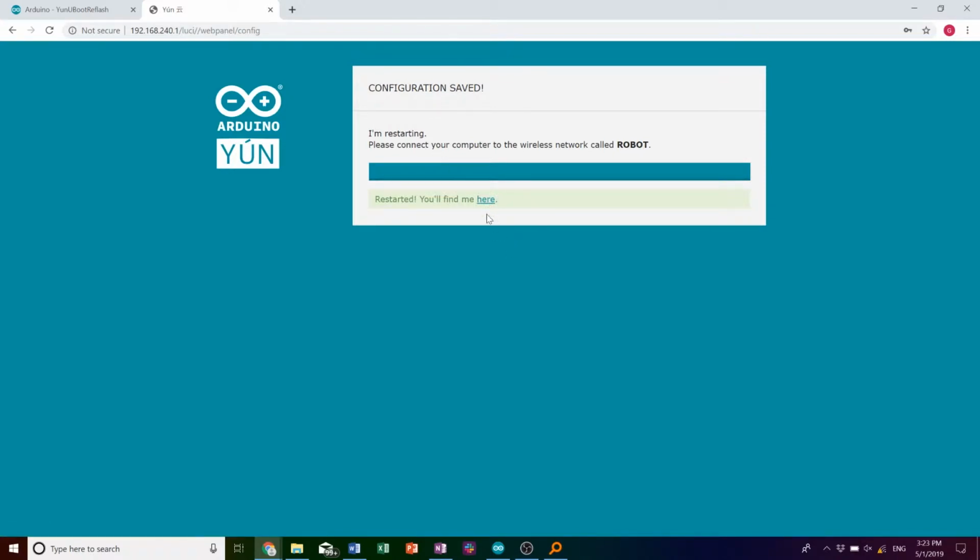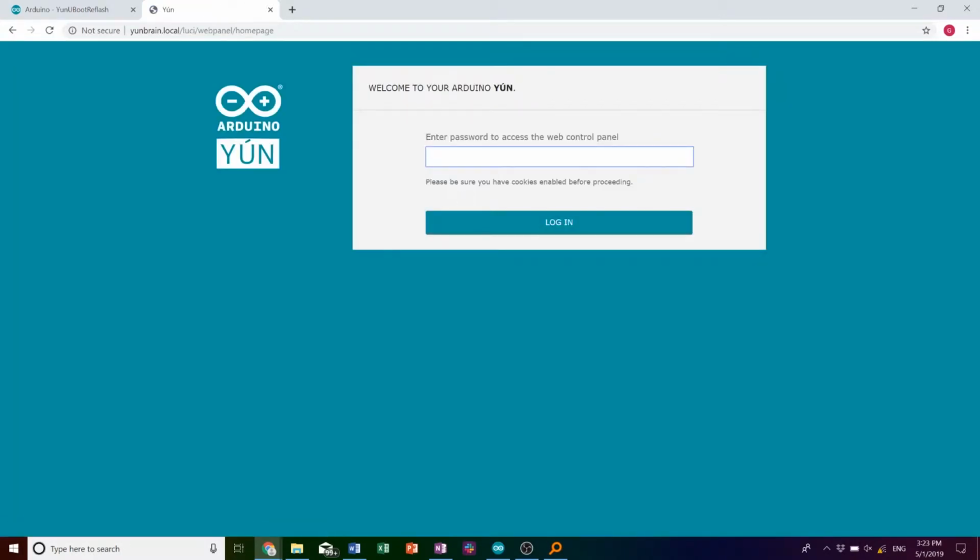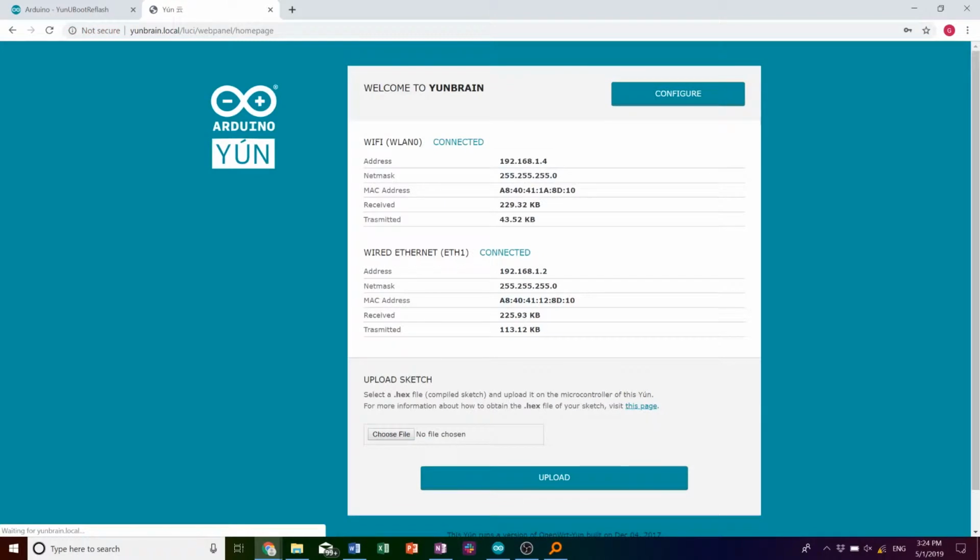Okay, so once the Yun's restarted, you can access it by clicking here. And now I'm at yunbrain.local. Great. I'll put in my password and log back in. Great, and now I can see that my IP address is 192.168.1.4, and my wired Ethernet access is 192.168.1.2, and we saw that before because we've been wired this entire time.